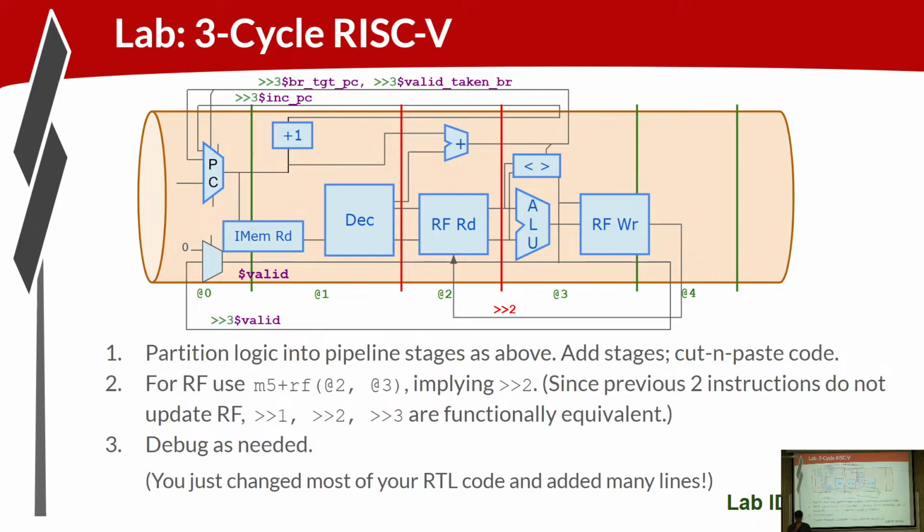We did in fact partition our logic. We made the register write a 2-cycle loop just by changing the macro parameters. And we made the PC update a 3-cycle loop. So we don't have to worry about the hazard cases being wrong because we're still only executing instructions every 3rd cycle.